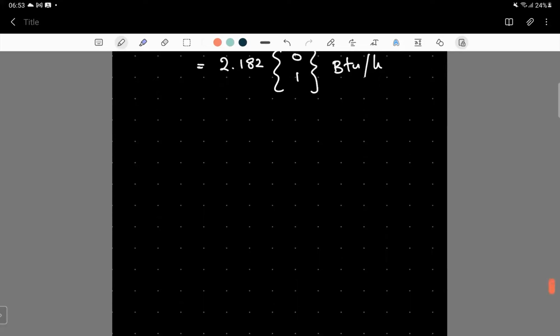We can assemble the stiffness matrix and write down the total structure stiffness matrix, along with the boundary conditions. The total structure stiffness matrix would be a 5 by 5 matrix, and if you apply the direct stiffness method correctly, you would get this matrix.